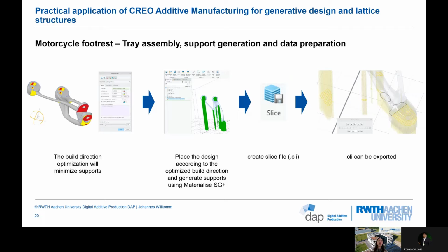It is typical that in your organization you spend a long time, a lot of hours, defining the parameter settings for a material for one printer technology. So your support parameters for the printer you have and the material you use, and when you have defined these settings, those can be saved in a parameter profile to be selected and used to generate the correct support structure.